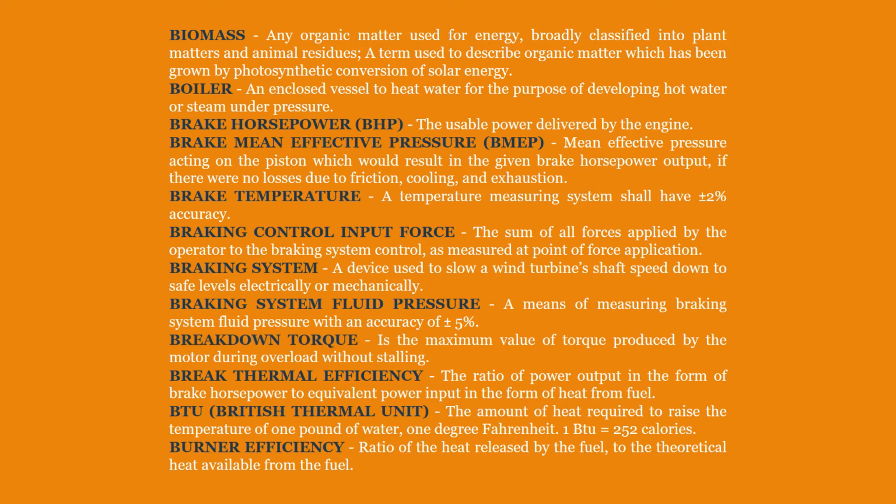Braking control input force. The sum of all forces applied by the operator to the braking system control, is measured at point of force application. Braking system. A device used to slow a wind turbine's shaft speed down to safe levels electrically or mechanically. Braking system fluid pressure. A means of measuring braking system fluid pressure with an accuracy of plus or minus 5%.